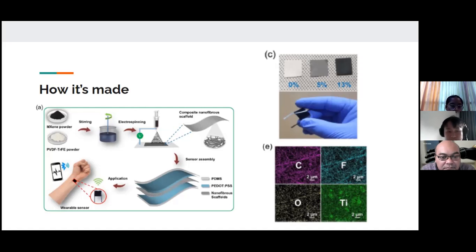After the spin coating, the film was kept on a hot plate for an hour at 60 degrees Celsius for drying. To increase the conductivity, the film was post-treated with DMSO and dried inside a convection oven for 15 minutes.